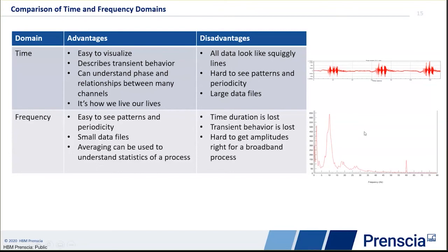If you see a frequency domain, the x-axis indicates only the frequency, and the y-axis may be a PSD or something, G square per hertz, or amplitude in G. So you may not know over how much time frame the entire frequency signal was produced if you don't really have the time domain signal. If somebody gives only the PSD, it is very tough to see how much time was taken to collect this particular signal. But statistically, it is possible to reversely generate some time signal. But at first look, it is very difficult to understand.